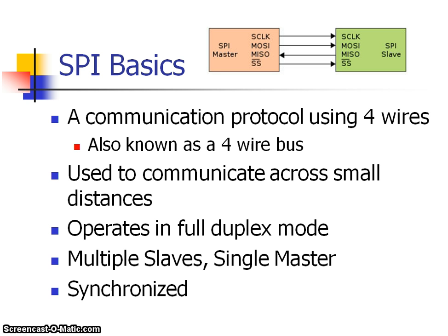Serial Peripheral Interface Bus or SPI bus is the synchronous serial data link standard named by Motorola that operates in full duplex mode. Devices communicate in master and slave mode, where the master device initiates the data frame. Multiple slave devices are allowed with individual slave select lines.